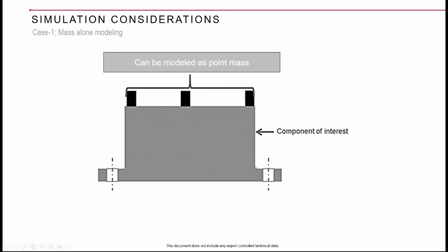Now my area of interest is the stresses on the lugs here. For this kind of scenario, all these solenoids as well as the unions or any electronic devices mounted onto the manifold, I can model as a point mass because their stiffness is not having any significance in adding a behavioral change